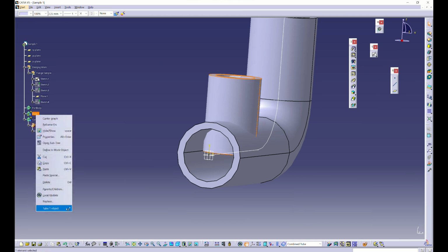Once again, let's go to the object, and using this we have these types of Boolean operation: assemble, add, remove. What is the difference between assemble, add, and remove? Add, by its name, adds the body, and remove removes the body. If I remove the body here, with a symbol, it's actually the same as add.